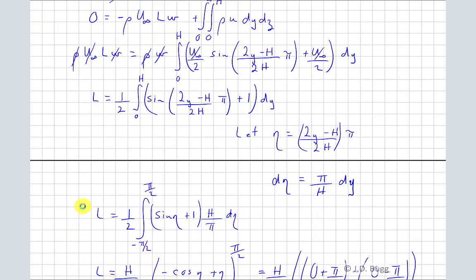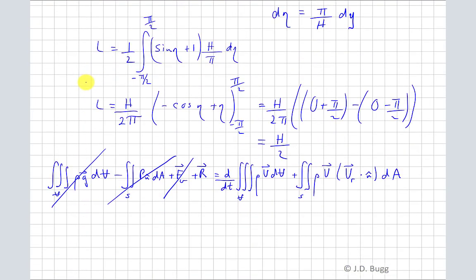So going back to our linear momentum equation, we're going to keep that. That's what we're trying to find. When we did the conservation of mass analysis, we already assumed it's a steady problem, so that can be crossed off. And we already talked about the fact that we have a uniform inlet and a non-uniform exit. So that'll have to be taken into account when we write this term out. So just cleaning this up, we have our reaction force alone on the left-hand side.